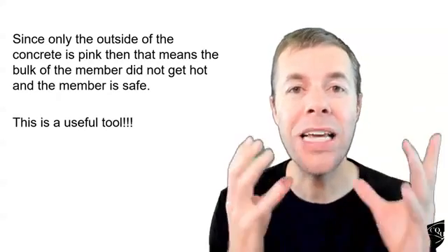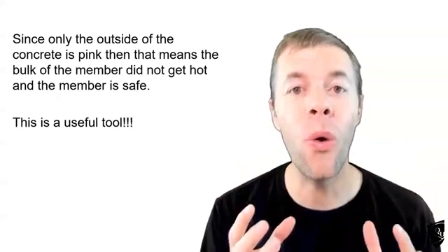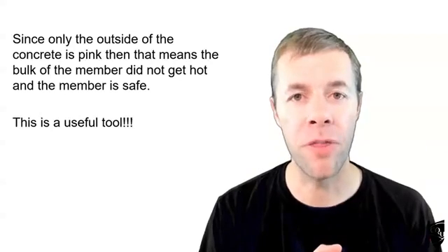This is a crazy, crazy useful tool to evaluate how they perform in the field. You basically look at the aggregates from the outside of the concrete to the inside, and you should see this color change. And you can do some testing after the fact if you need to in the aggregate to kind of back into what that color change is. But this is insanely useful to figure out at what temperature and at what depth it's made it inside your concrete structure.